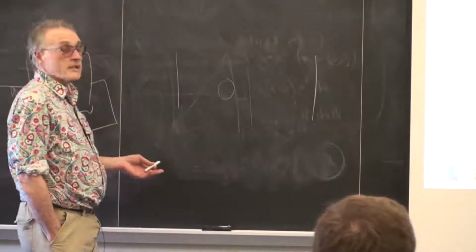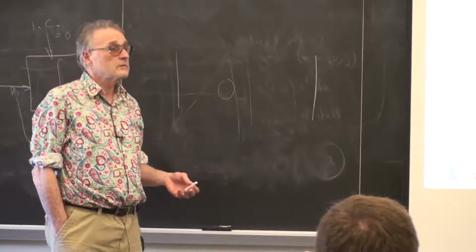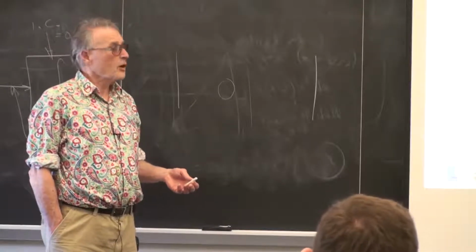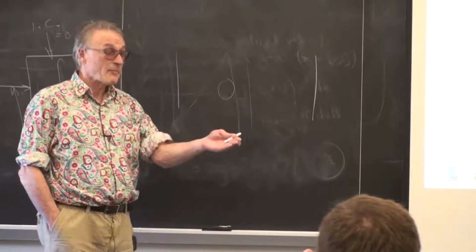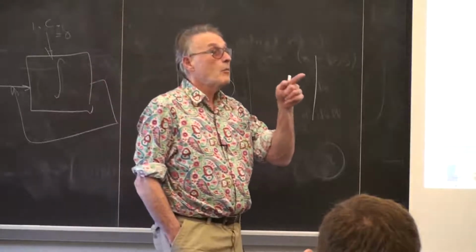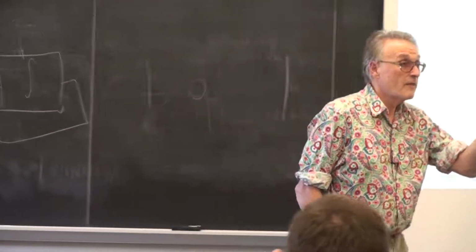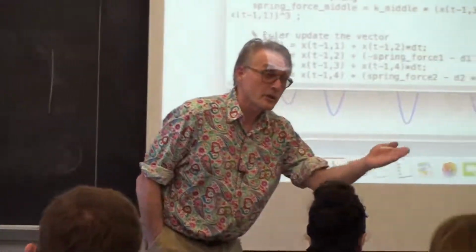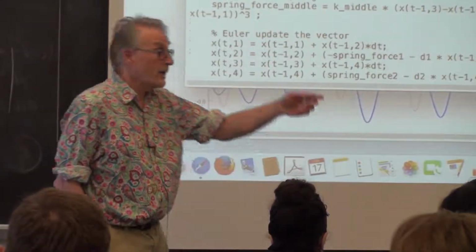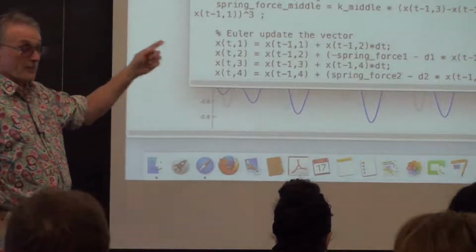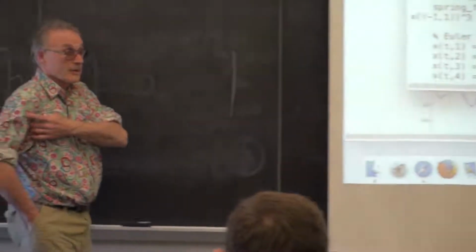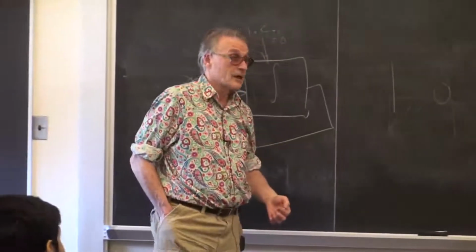So, yes, that will do it. So don't do that. You make sure it doesn't happen by the initial conditions, and by simulating in Matlab the very set of constants you're going to use in your Verilog. And it better work in Matlab, and it better not go outside the bounds at any time.